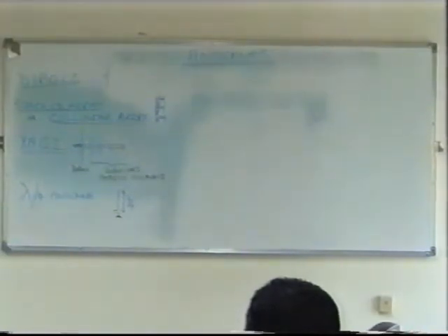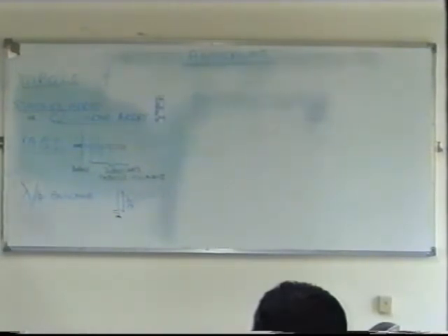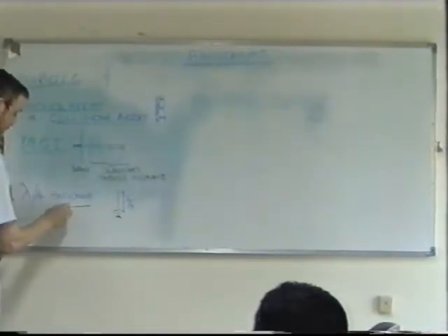Basically, they change the characteristics of the antenna to match the particular transmitter or receiver that they have in the car. Do you mean the aerial gain? It doesn't do anything to the gain. The gain is to do only with directivity, with direction. It's really matching impedance.